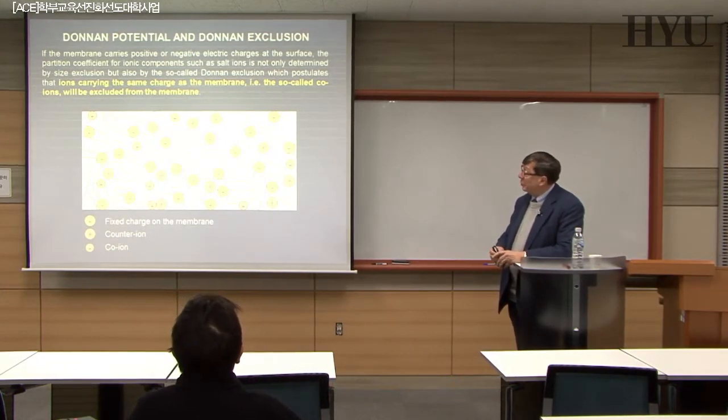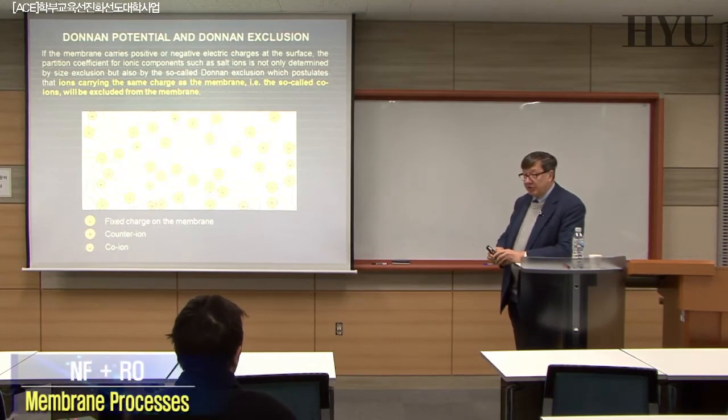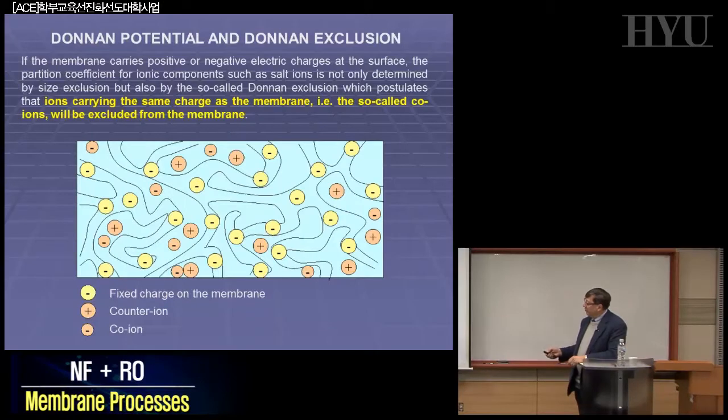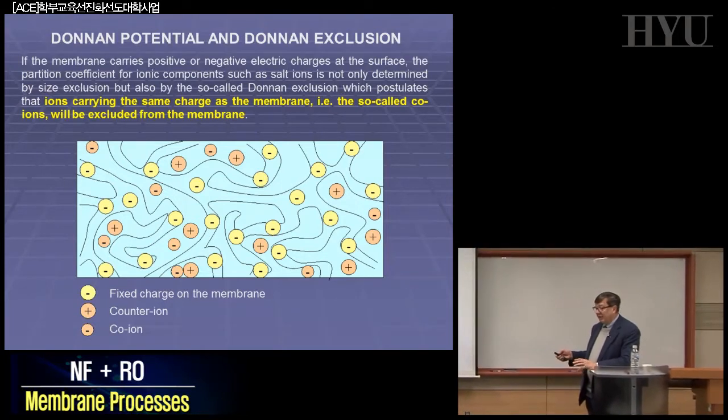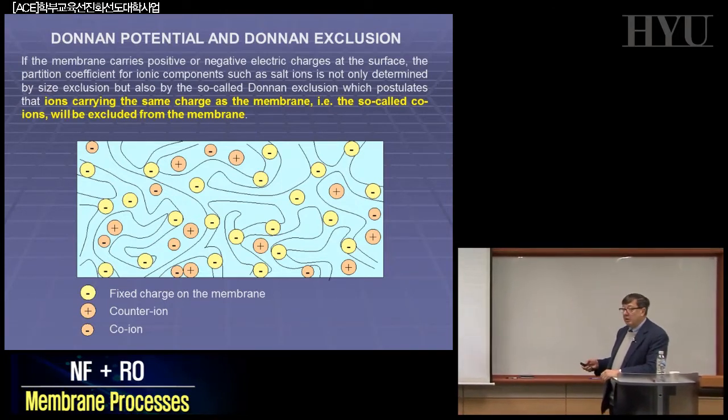Last time we started to talk about nanofiltration. And we have been mentioning that in nanofiltration, for the first time, we are also introducing materials where the selectivity can be related not only to the size, the dimension of the particles and the dimension of the pore, but also to the fact that the membrane material can be charged.